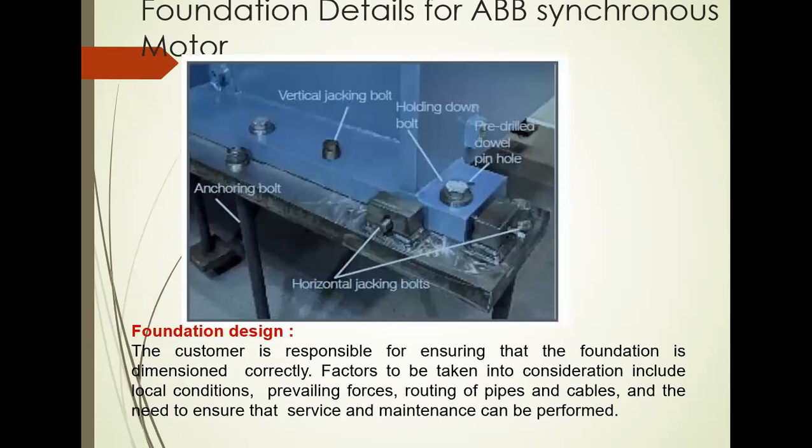Here you see foundation details of ABB synchronous motor. Here we have the level bed arrangement. Some of the bolts here: vertical jacking bolt, anchoring bolt, horizontal jacking bolt, holding down bolt, pre-drilled down pin hole. So these are all the parts of that bed plate. Okay, the ground level, it is above the ground level. So these bolts are needed for mounting the machine.